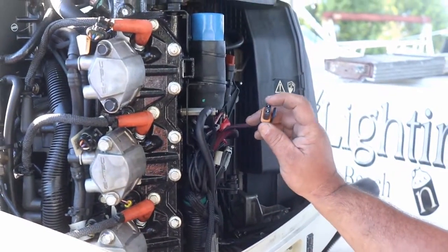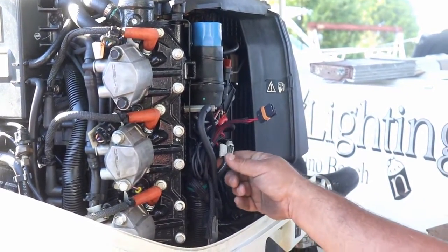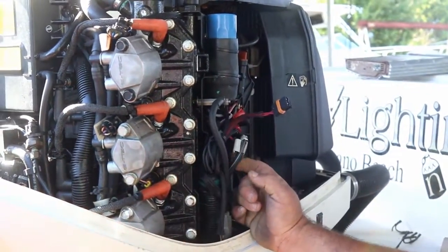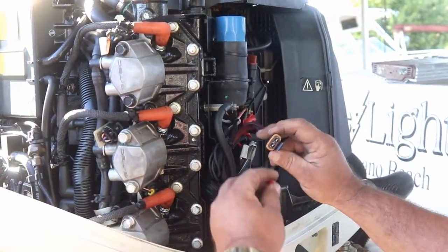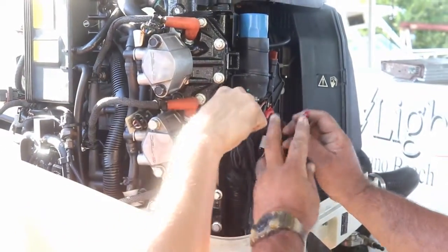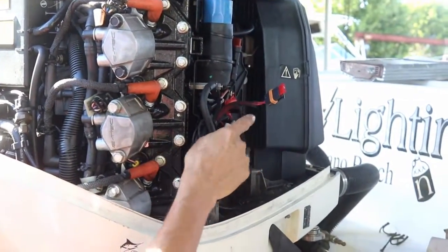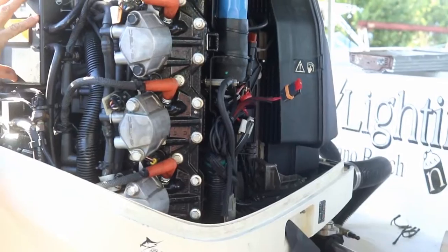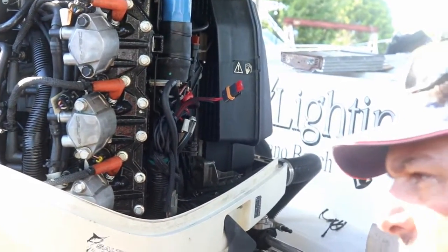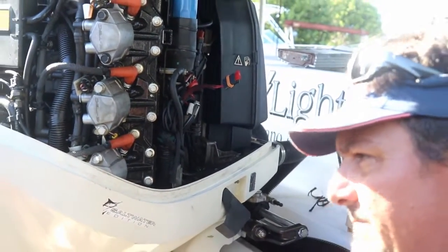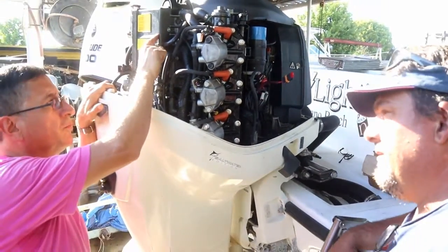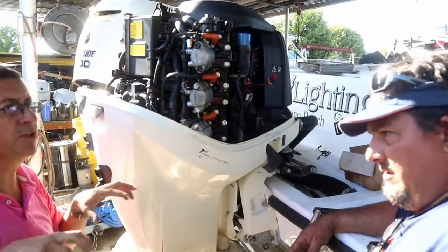This power comes from the battery cable that comes from the battery and goes back to the other one. This cable continues over there and brings the power to the computer, which has to have a minimum of 9.5 volts in order to stay running. Minimum 9.5 on the computer, and the computer starts with the distribution of current.